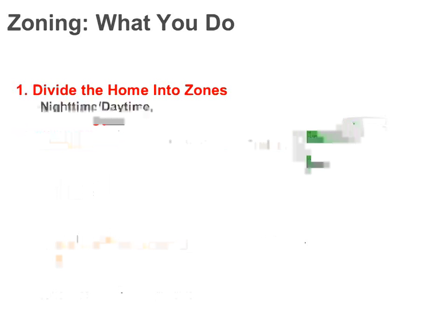And then think about specialty areas. Home offices are a fantastic one that need their own zoning. Guest rooms, they don't need it, but it's kind of nice. When the mother-in-law comes to visit, she can have her own temperature, and you don't have to crank the heat up for your whole house, just for her. Basement's probably another one, and then the bonus rooms above the garage. Those kind of areas probably do really good with their own stat.